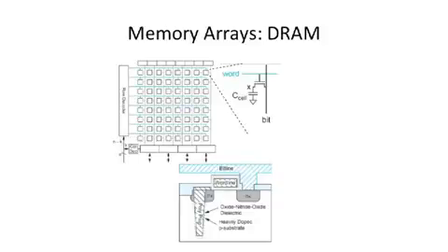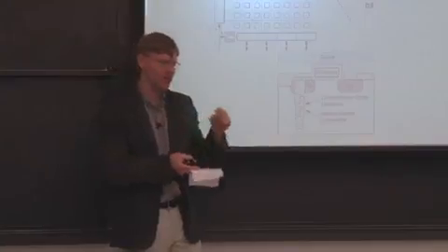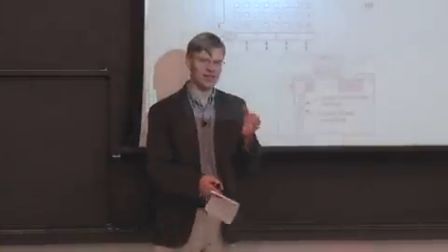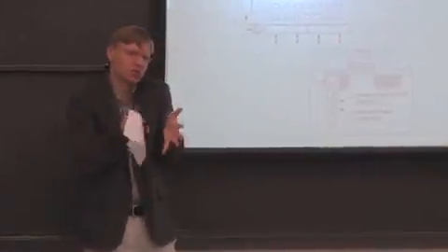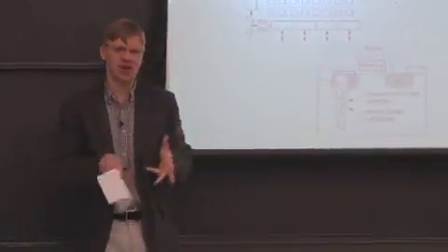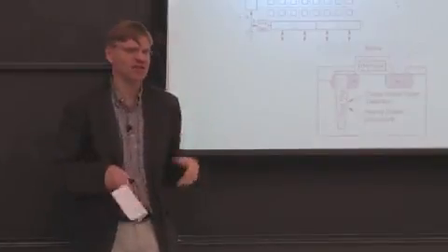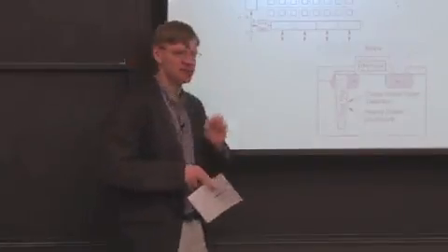It is a capacitor, but it's a very oddly shaped capacitor. Typically, what will happen is you build these very, very deep trenches, very long and skinny trenches. They're skinny because you want to put them very close together, because if you want gigabytes and gigabytes of RAM, the smaller you make it, the more you can shove on a single piece of silicon.